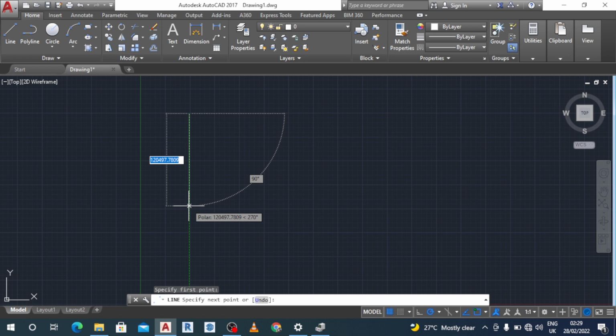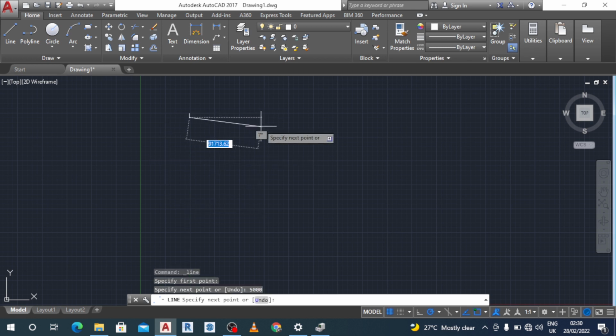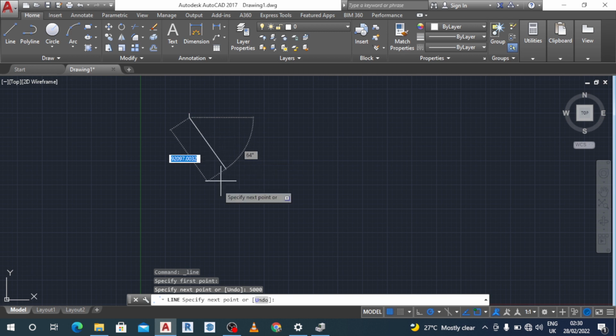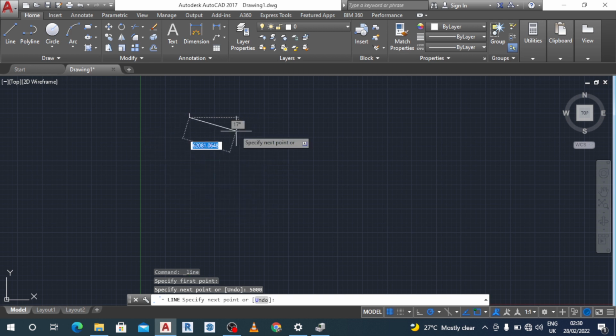So if you want to insert 5 meters, that will be 5000 mm. Take note of that. So we insert 5000, then enter. As you can see, it's small. Whenever we're done with a tool, then escape. We will always press escape whenever we're done with a construction tool.